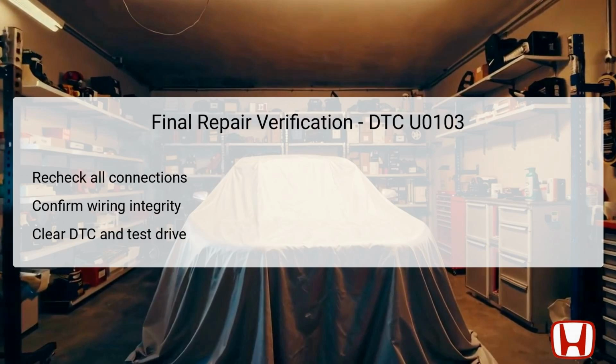After completing all troubleshooting steps for DTC U0103, it is essential to carry out a final repair verification process. Begin by double-checking all connections that were serviced to ensure they are secured correctly and devoid of corrosion. Additionally, confirm the integrity of the wiring throughout the communication paths established.